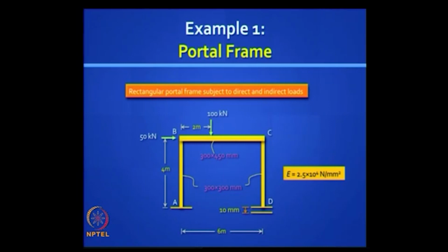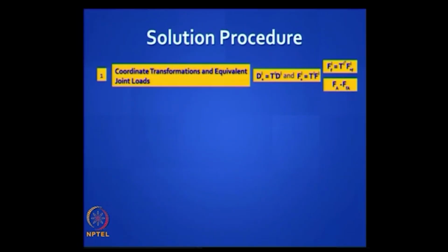But more important, we must know the support reactions, we must know the bending moment diagram, the shear force diagram, the axial force diagram, which is all easy once you have the free bodies. Okay, so how do we proceed? Well, again this procedure is very familiar to us. We are following exactly the same steps.